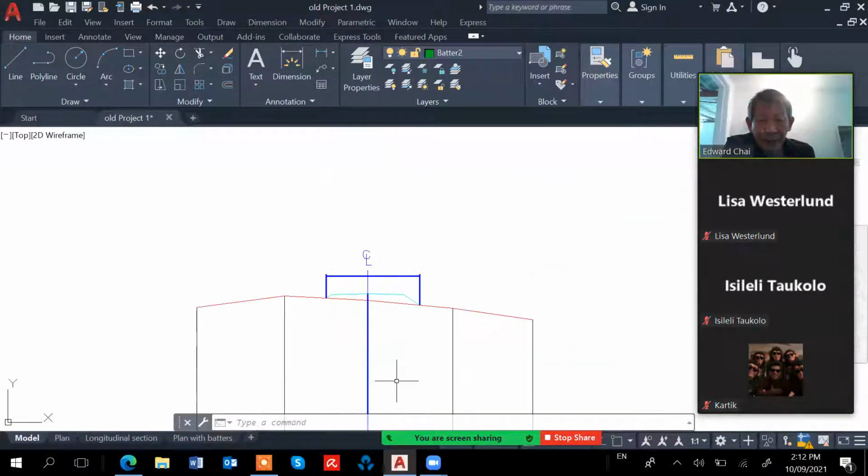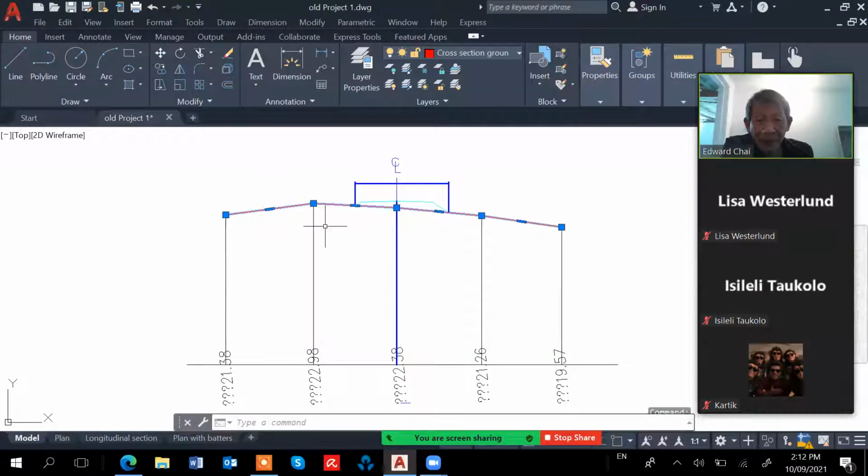all this thing, I did this is the ground level, the existing ground level from the spot height. Actually, this one is different from what you guys are doing this time, because this time I said, you just concentrate on the contour, just the contour. You locate the intersection of the contour with the cross section line, and then that one is easy. You just have like 20, 22, 24, because the contour is about a 2 meter interval, so you get the exact values.